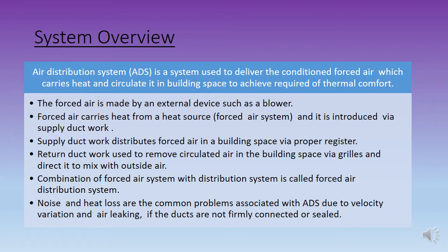Register. What is the difference between register and grill? Well, a register is for supply ductwork, the outlet of supply air into the space, and a grill is for return air.